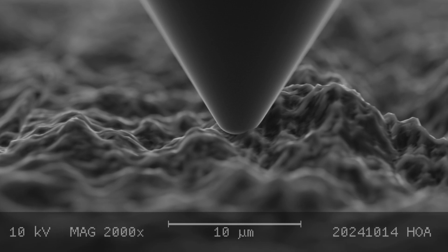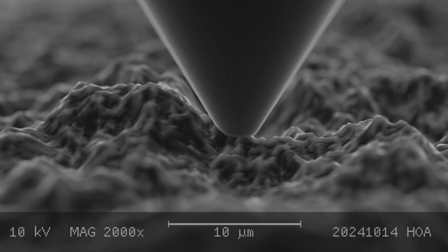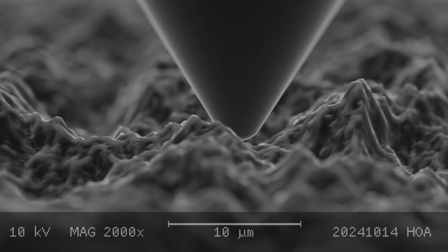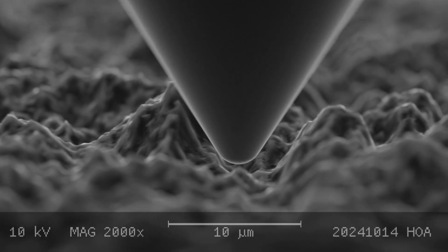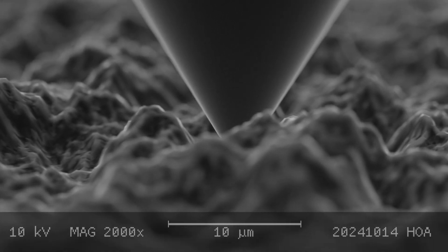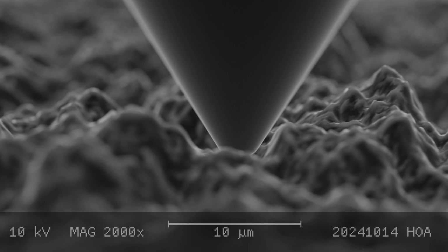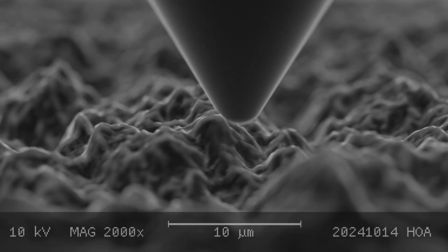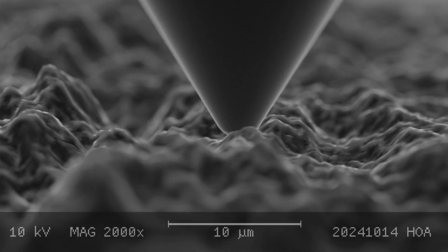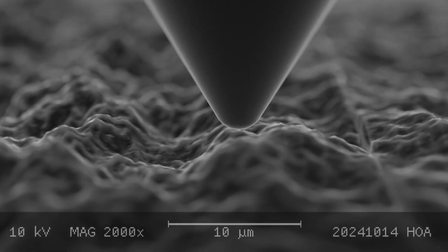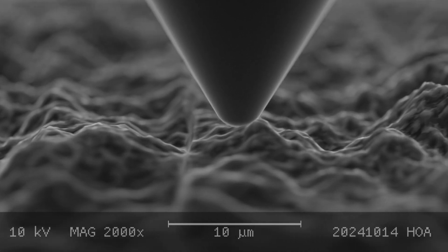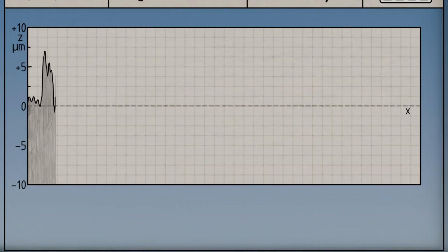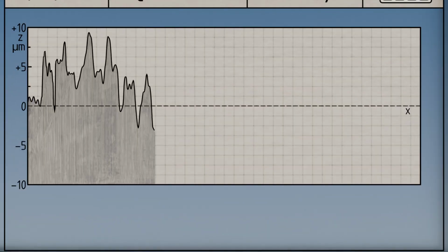Depending on the measurement conditions, a length of about 4 millimeters is scanned at a speed of approximately 0.5 millimeters per second. Because vibrations occur at the stylus when passing over edges in the roughness profile, which can distort the measurement results, such short wavelength oscillations are filtered out by a so-called low-pass filter via software. We will discuss the filtering in more detail later, as it is central to the significance and comparability of surface roughness measurements. The filtered up and down movements of the stylus result in a recorded two-dimensional primary profile.